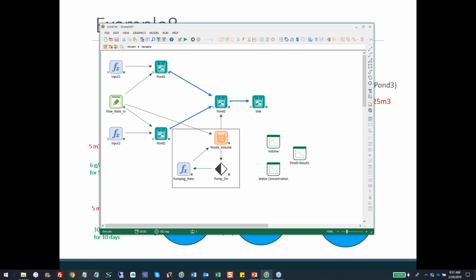That's what you do. You're going to keep track of the flows. You know how much water is in the system. You know what the flow rate is. Once you've built your water balance model, then you might build your contaminant transport model. Say, okay, now that I've got a water balance model, now I also want to do some water quality calculations. But those things have to be coupled, right? Because these volumes and the flow rates are not constant. They could be changing with time.